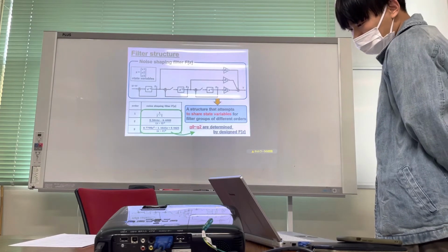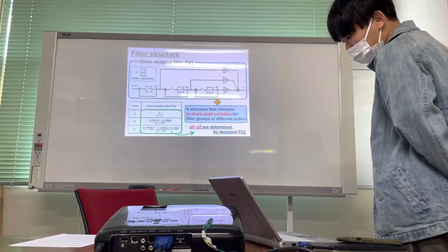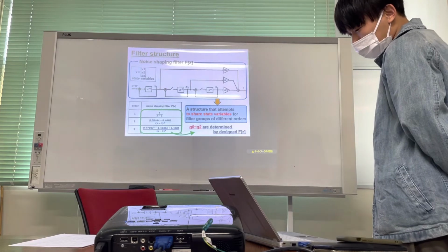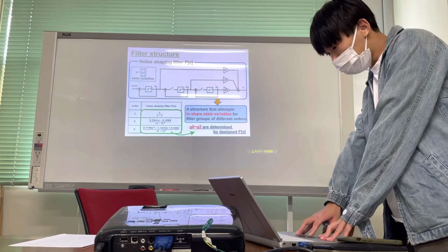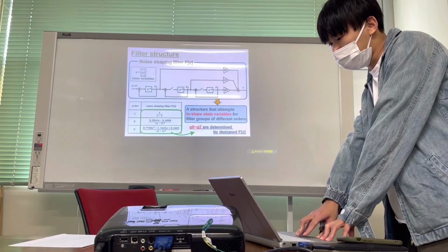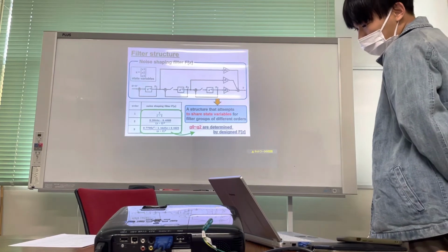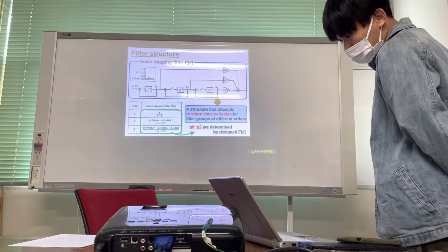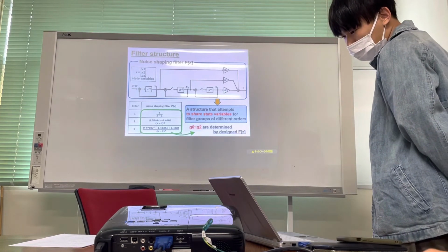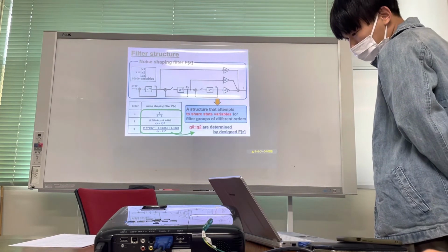One factor that causes instability when switching filters is that the internal state of the filter changes. Therefore, a filter structure that ensures continuity of state variables is considered suitable for filter switching. In this work, we attempt to secure stability by suppressing state change due to switching, by making the noise shaping filter the following filter structure with only output coefficients.